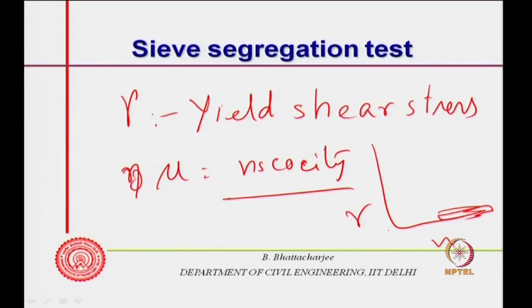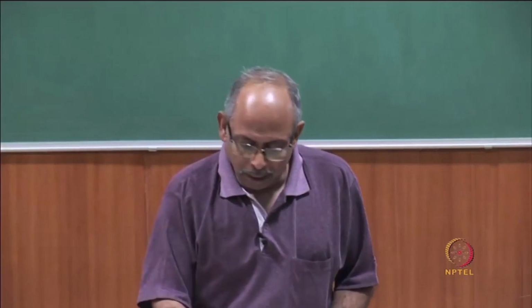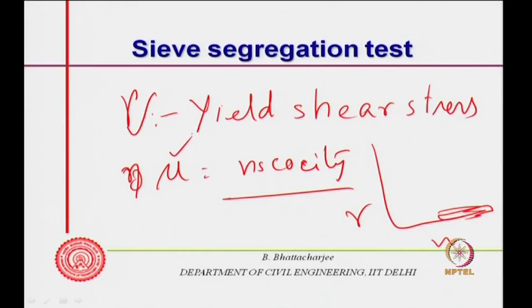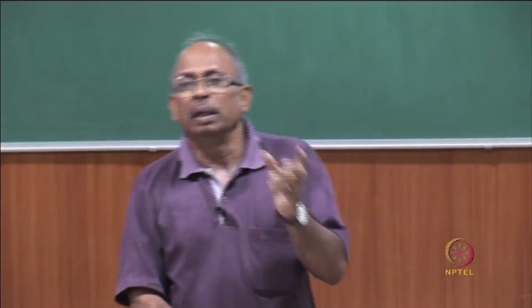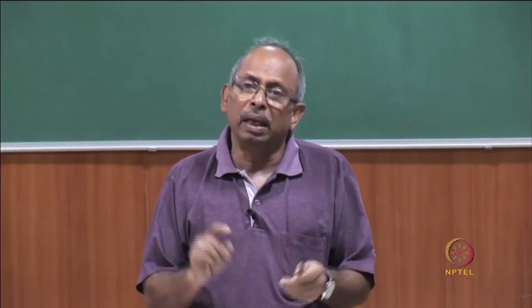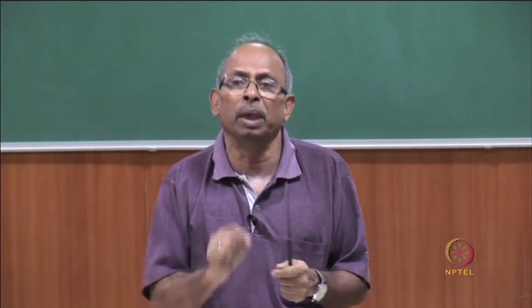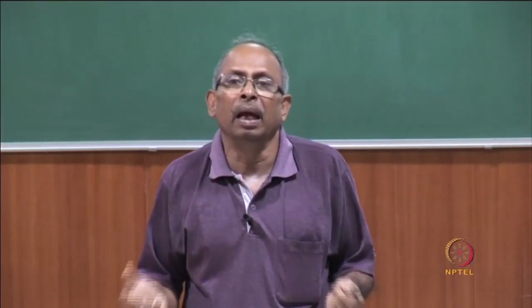But there is no universally accepted method to measure gamma or mu, the rheological properties. Supposing we could have done this, we would have said that for being self compacting, only one rheological measurement determines gamma as well as mu, and if gamma ranges from 0 to something and mu ranges from this to this, then I will call it self compacting.